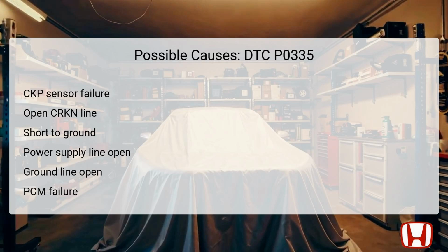Several potential causes can lead to the activation of DTC P0335. Firstly, a failure of the CKP sensor itself is a primary suspect. If the sensor is defective, it will not generate the necessary signals.